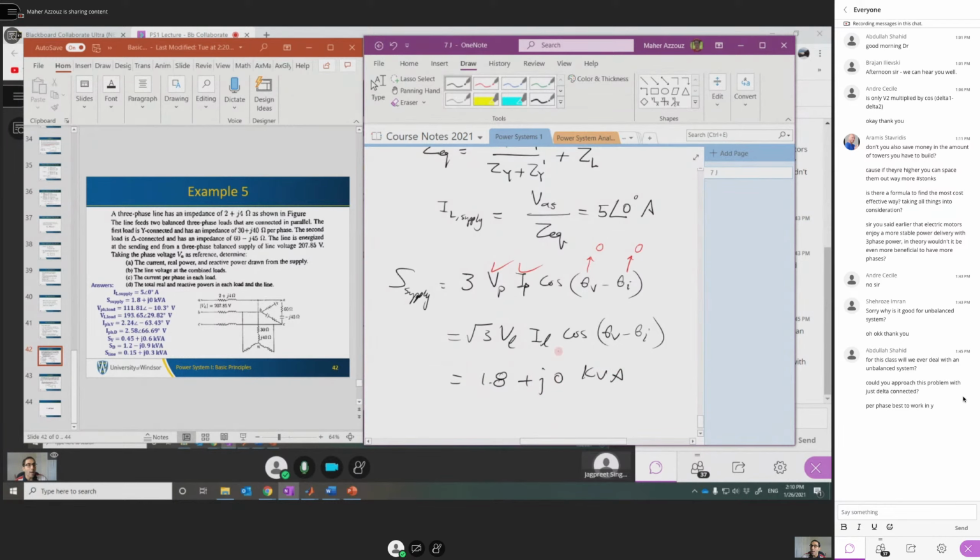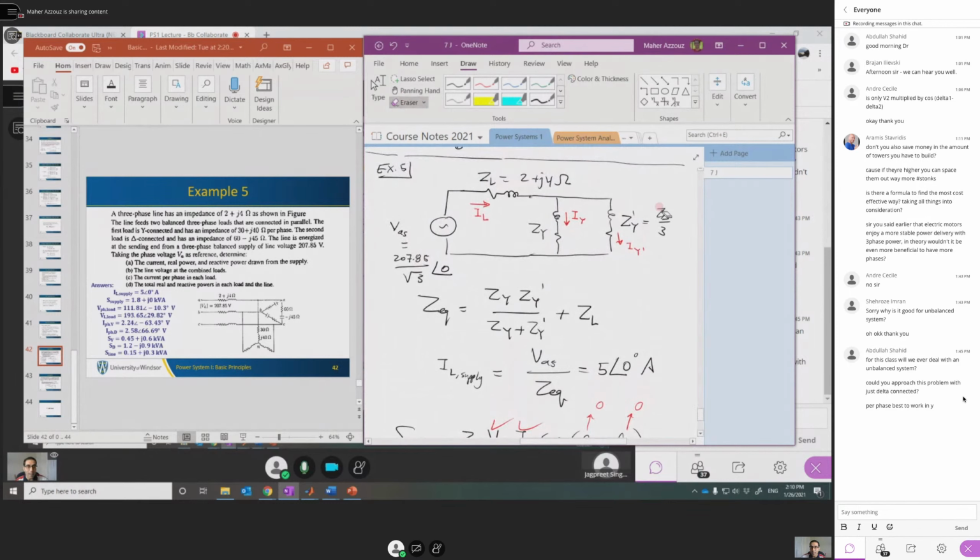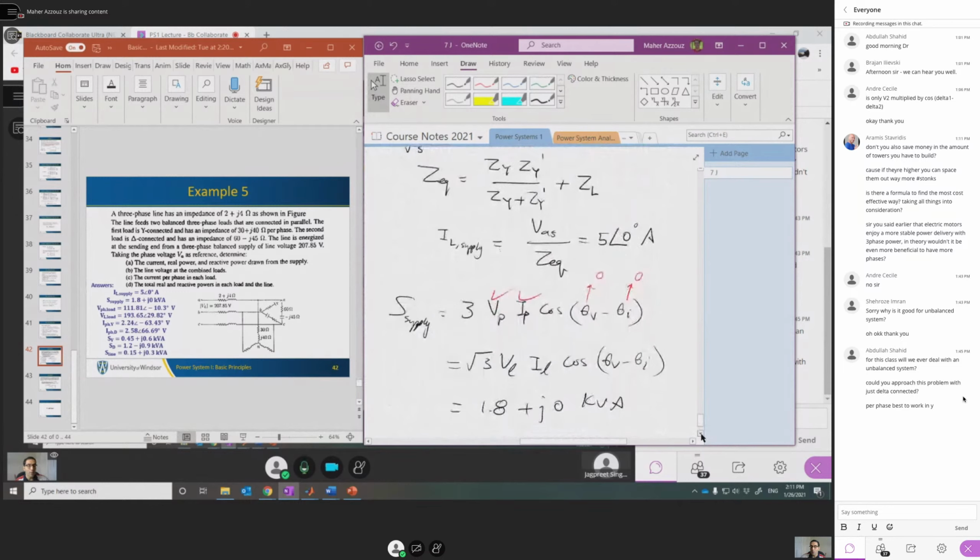As you can see, we don't have any reactive power. We have all the active power. This happens because the second load is capacitive. It has a capacitor bank, as you can see here. So this capacitor will generate reactive power locally to compensate all the reactive power needed for the line and the second load. That is why the total reactive power needed from the supply is 0.